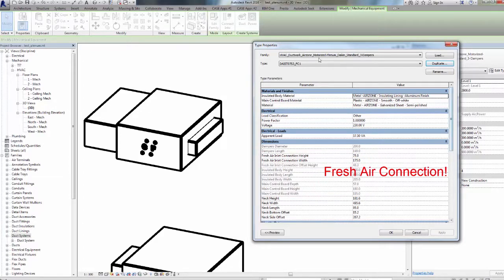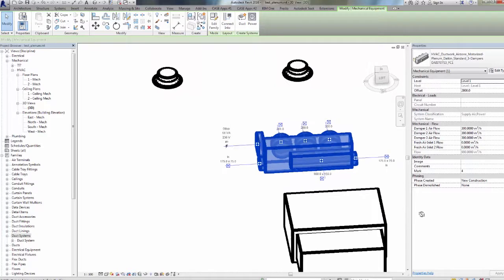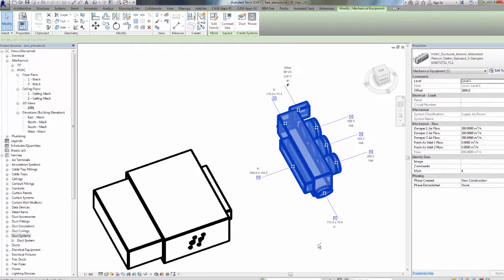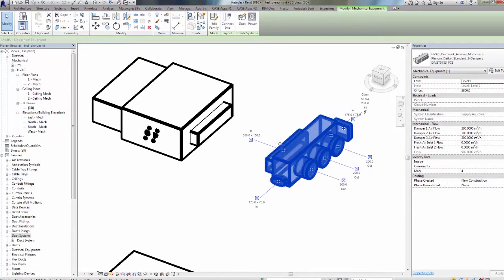Once a new type is created, we are modifying the dimensions so the neck has the correct ones. As shown, when modifying the neck dimensions, the plenum is not displaced. If we needed to adjust the gaps when changing width and height, it could be done by means of the interior gap and the side gap. The usual will be to add or deduct half of the difference that was added or deducted towards the original dimensions.